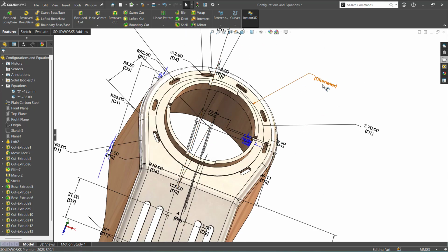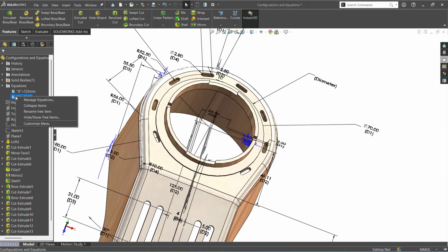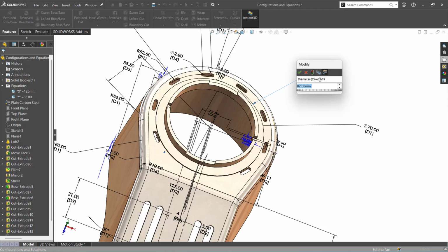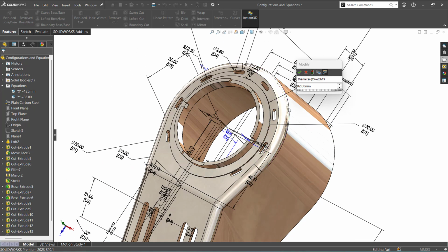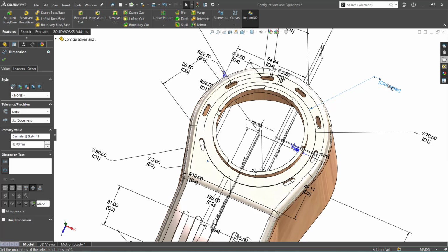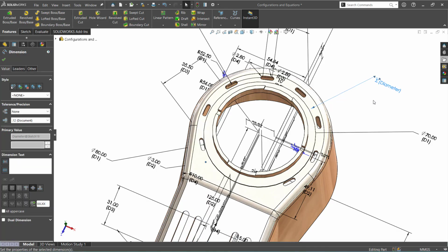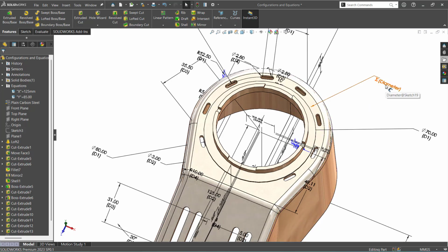Now I want to check this much. How much here is it? 82, right? What we'll do is, it is already 85. This is the outer one, right? He has taken this dimension. Let's do one thing. Instead of this value 82, I would like to assign 85. What do we do? Just double click on this dimension. Now here you remove this and press equals to global variable y, green check.